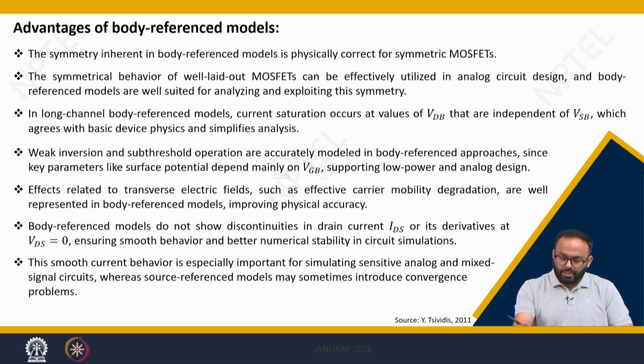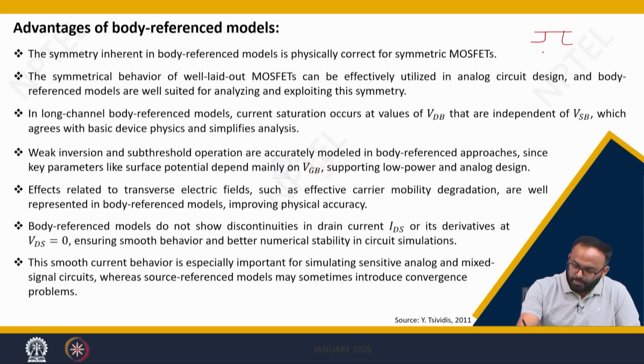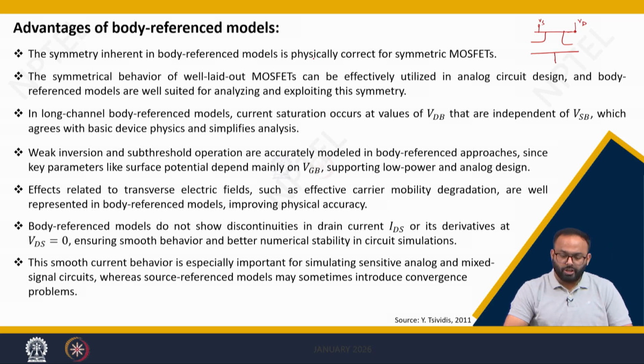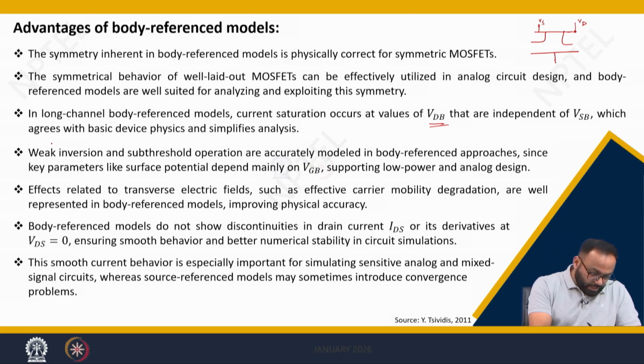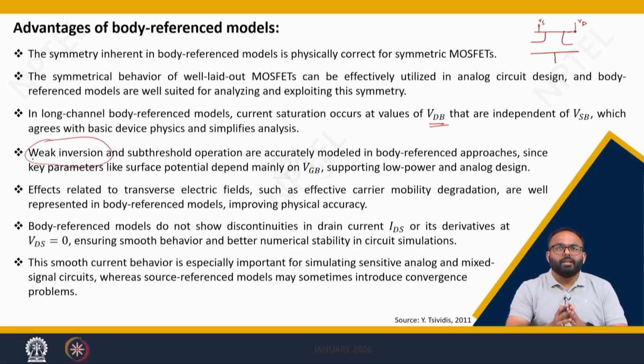because the body reference model gives a new intuition which inherently captures the symmetry of the device, meaning if you have Vs here and Vd here, then the body terminal actually maintains the inherent symmetry of the symmetric MOSFET. The symmetrical behavior of a well laid out MOSFET can be effectively utilized in analog circuit designs, where this body reference model will be used. In the long channel body reference model, the current saturation occurs at values of VDB that are independent of VSB, which agrees with the basic device physics and simplifies the analysis. Yes, the weak inversion operation is well defined in terms of the body reference model.